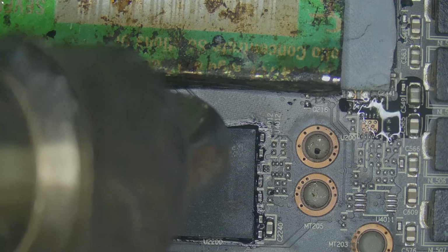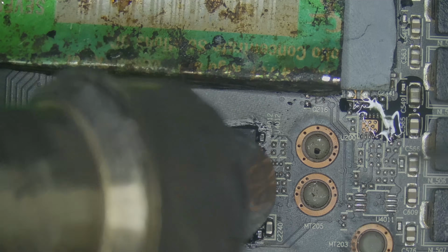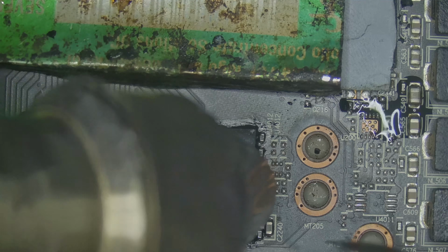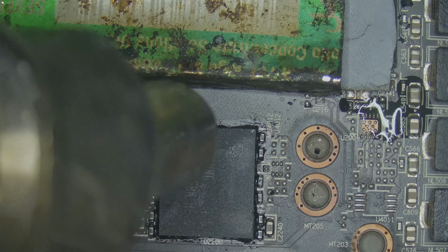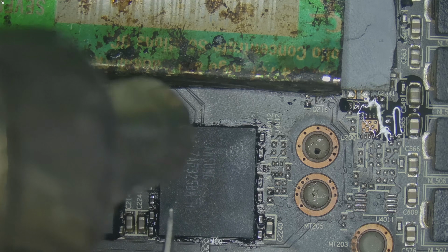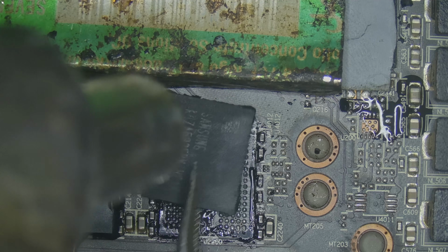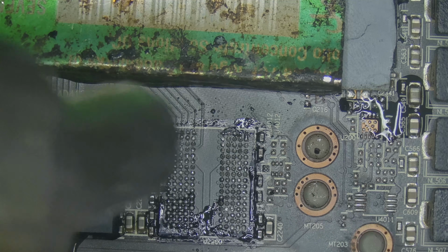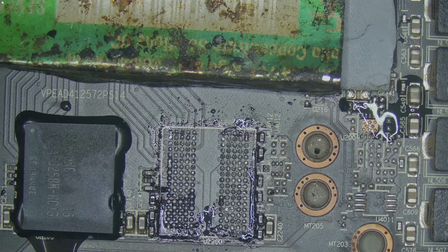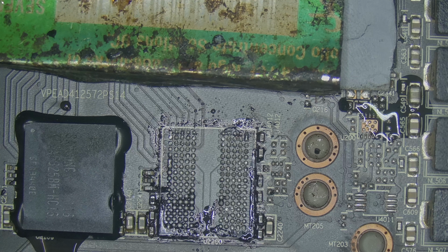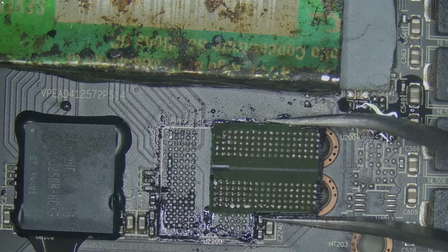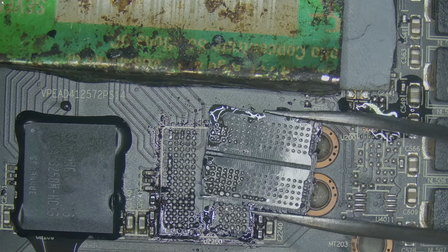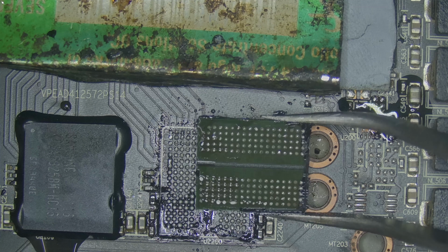To check if the solder underneath has melted, I gently test nearby SMD components. If they move, I know the solder is ready. Now, with tweezers, I insert into the center of the chip and carefully lift it. This part is purely based on judgment. If you lift too early, you risk pulling the pads off the PCB. But here, as you can see, we've achieved a clean lift. There are some gray pads on the chip, but that doesn't matter since the chip won't be reused.